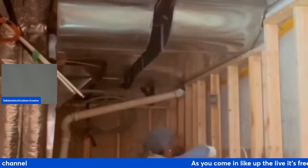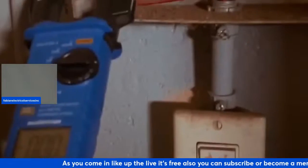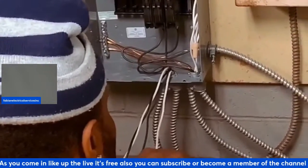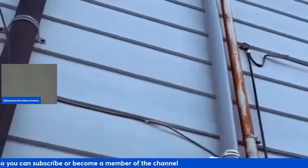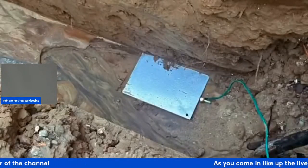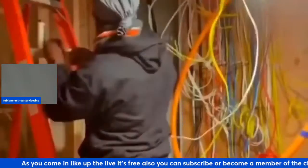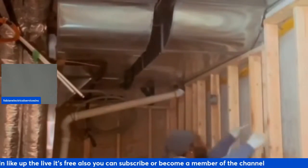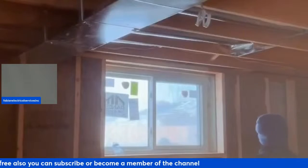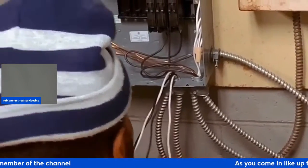So that was the explanation of the GFCI protection, AFCI breakers, and surge protection, again according to the OESC 2024 electrical code. And again, under the Canadian Electrical Code, your surge protection device must be properly bonded. If you're wiring a GFCI outlet or installing an AFCI breaker, remember these OESC 2024 updates.